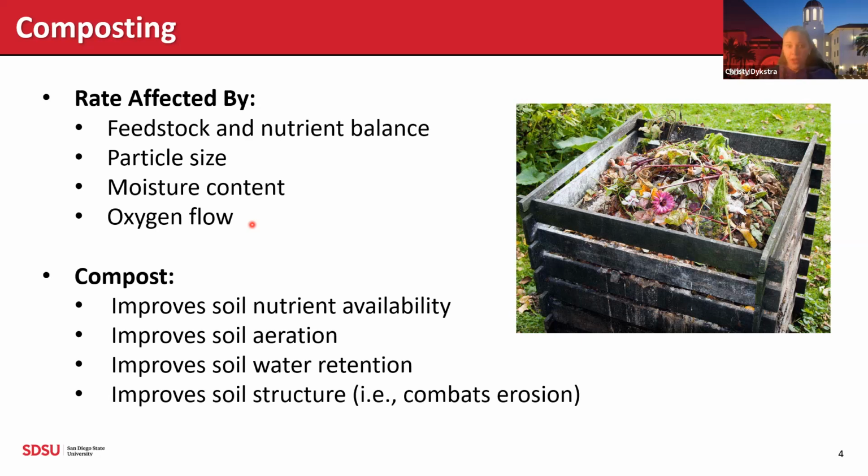So the output of all of this is compost. It's great for soil amendments. It gives nutrients. In fact, it can help aeration by allowing for a more fluffy soil texture that allows for more voids for oxygen to get in. It can improve soil water retention. So all of those voids, they can also fill up partially or fully with water and can help hold that water in place. And then it also helps to combat erosion. So it can be a great soil amendment for areas where erosion is an issue.